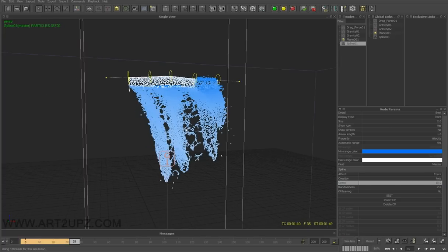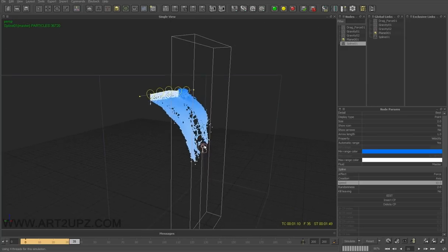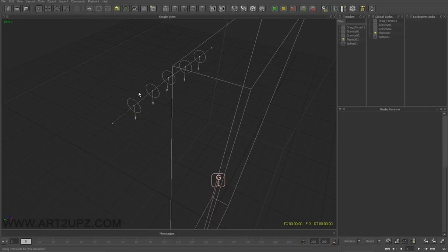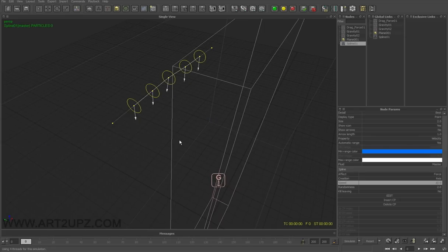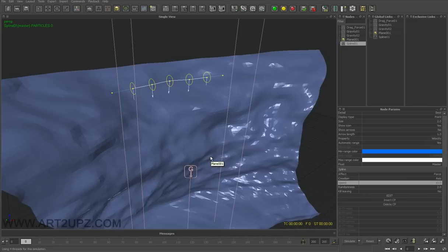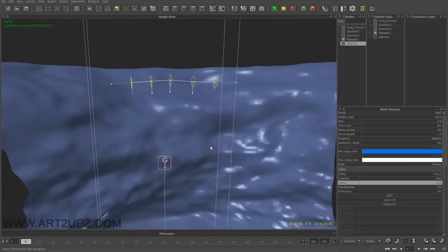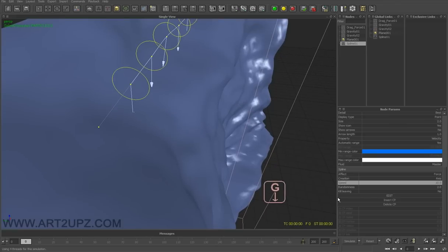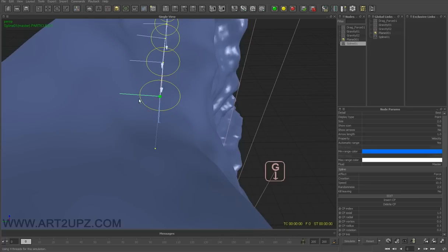Okay, I stop, and for example I can introduce another aspect. With 7 I switch the bounding box for all of my viewport. With 8 I activate the wireframe viewport, with 9 the shade, with 0 the shade with smooth shader. Okay, another aspect, I can select my spline and I go edit and I click on my points